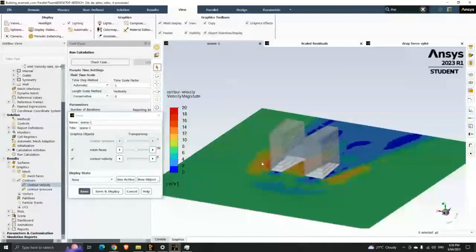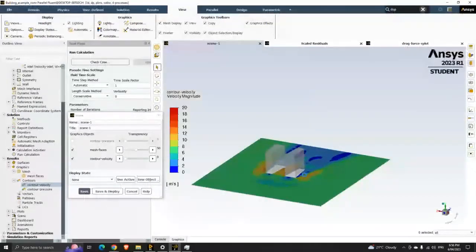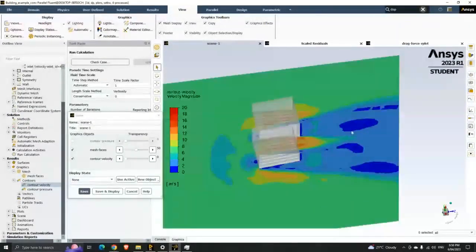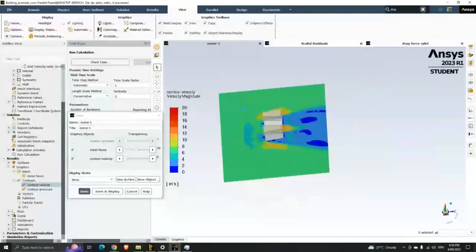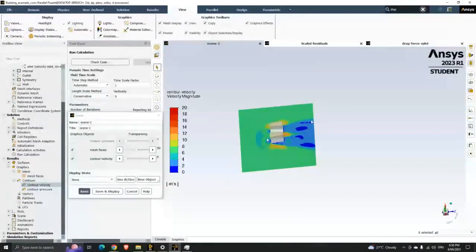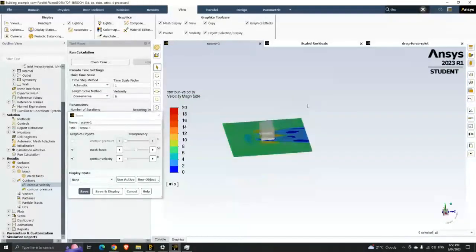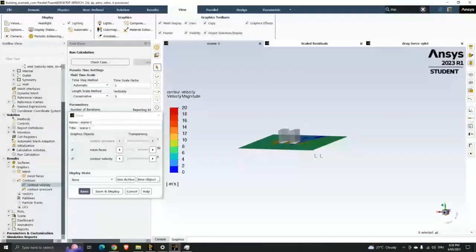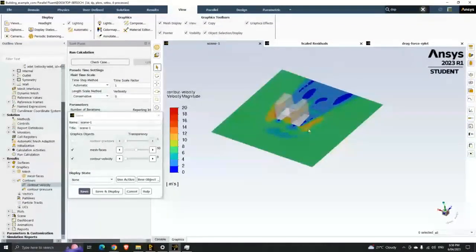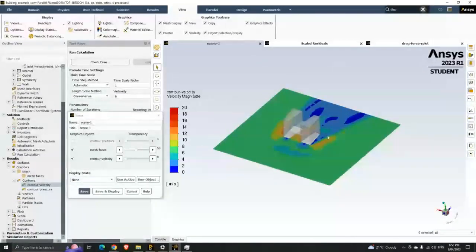One of the things I said is we need a very large domain around here, and the reason is, you see this blue region where the flow is really slow, that's the wake of the building. Ideally you want a big enough domain that this wake dissipates itself. Right now we are truncating this wake, which is not ideal, but because we don't have any more cells to play with, that's what we have done. You need a much bigger mesh to capture this wake properly.